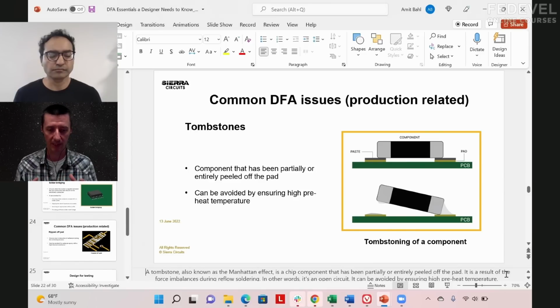When the PCB is very high density and there is only one place where you can put a via, you can't really choose if you would like to put it left, right, or somewhere. You just have to do it. And if it was so bad, then I'm pretty sure the assembly house would tell us every second component has problems, but they never tell us that. Yes, somehow they always find a way to fix it anyway.